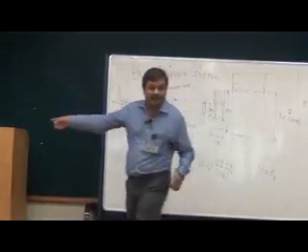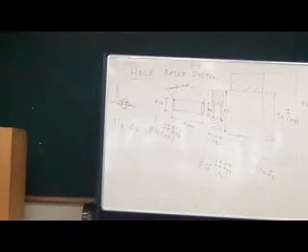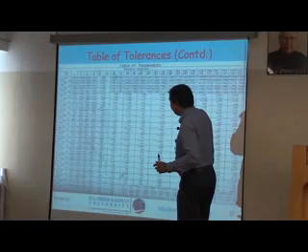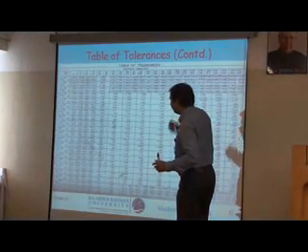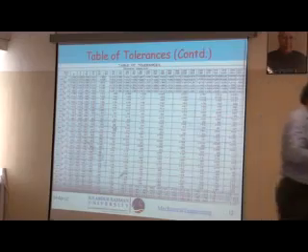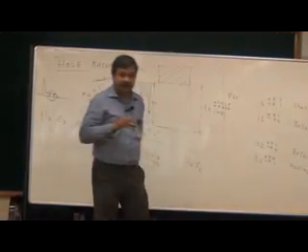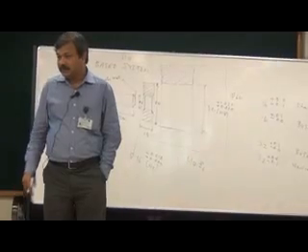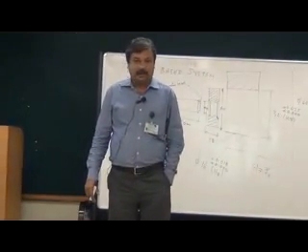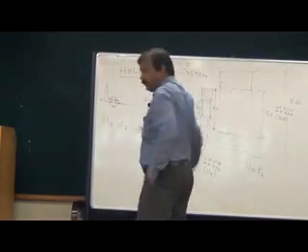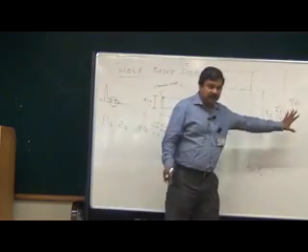For 32 diameter, I should go back to the table. H7 and 32, in the range 30 to 40. H7 is plus 25, plus 0. The dimensions given are in micron. Plus 0.025, 0. So this is for the whole feature.